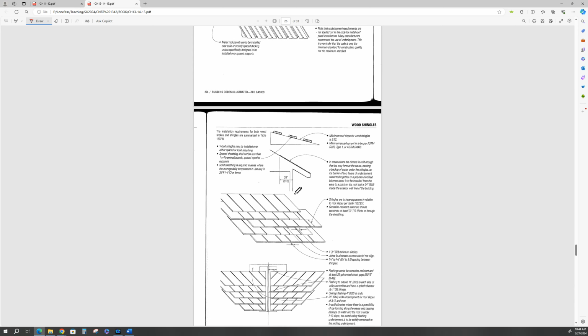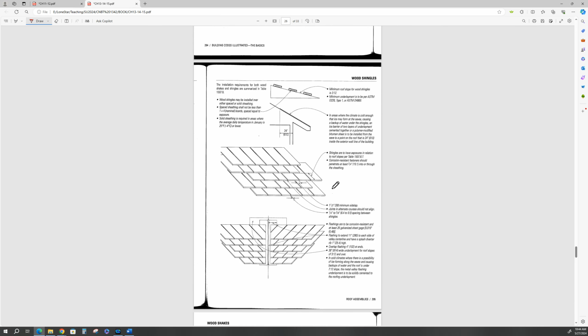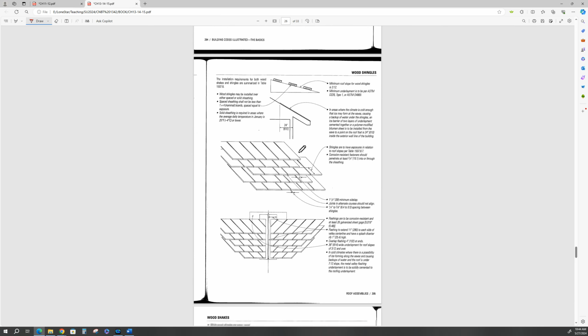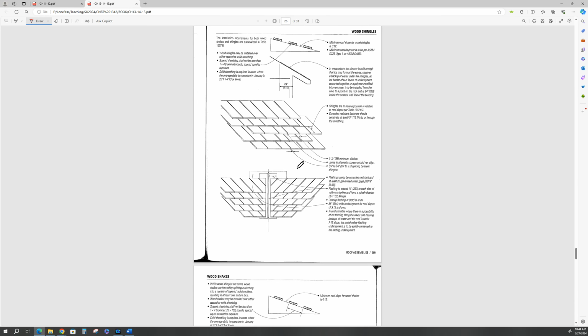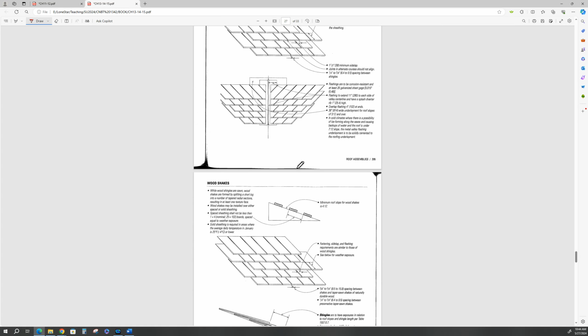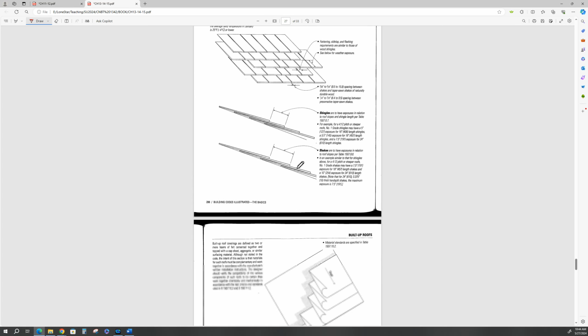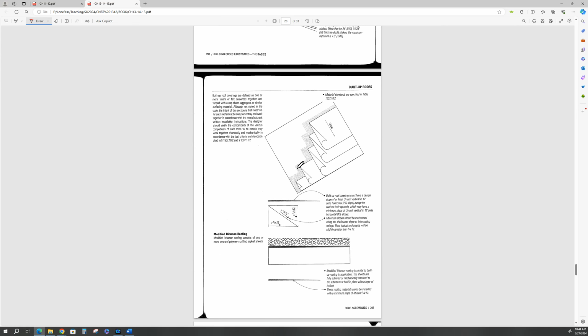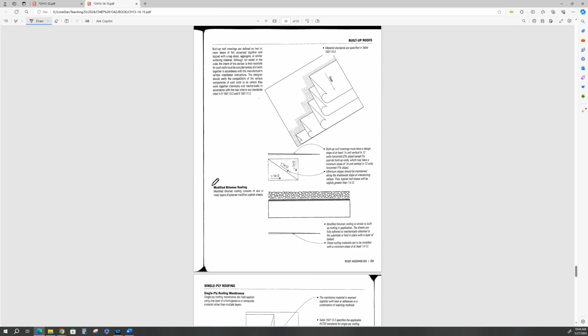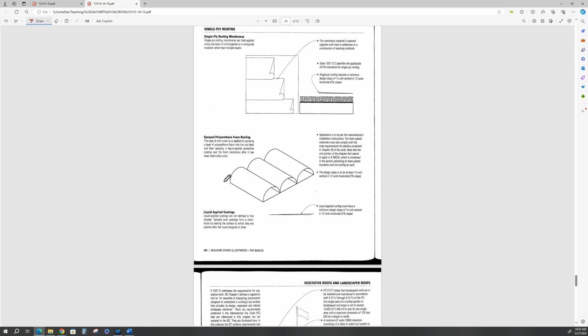All right. Wood shingles, I'll fire you if you put wood shingles on my project. Not going to happen. I don't care how quaint and pretty it looks. Go ahead and burn your house down before you move into it. Built-up roofs. You can spend a whole semester studying all kinds of built-up roofs and membrane roofs and stuff like that. Again, this is future problems for your next-door neighbors. You got high impact winds. The stuff gets old, the gravel gets loose, and boom, it just gets picked up and thrown like buckshot.